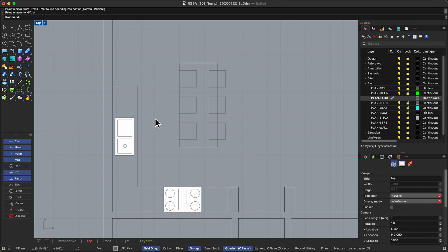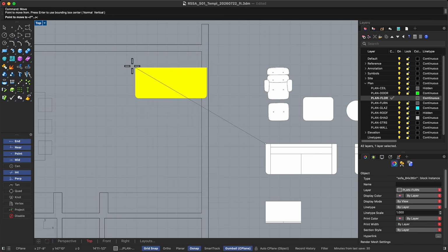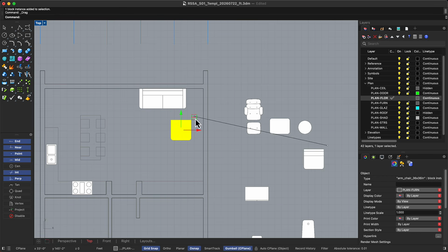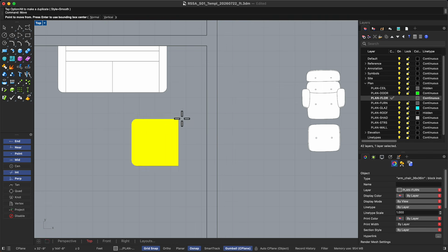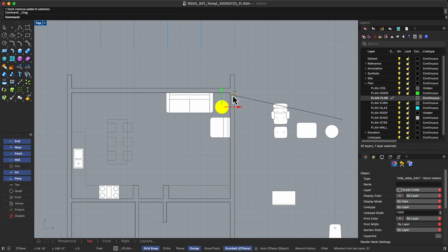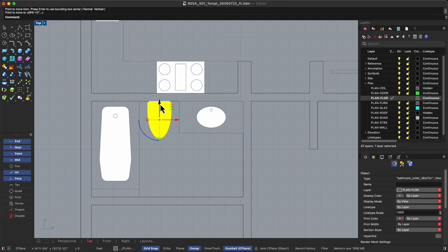Place a dining table beside the kitchen, then position the living area toward the strongest daylight and outdoor connection. Use the furniture to confirm that the entry path moves through the room without cutting awkwardly between the seating. If the layout feels compressed, move your partition wall. It is easier to adjust a plan while it is still line work than after it becomes a three-dimensional model. On the opposite side of the kitchen wet wall, place the bathroom.